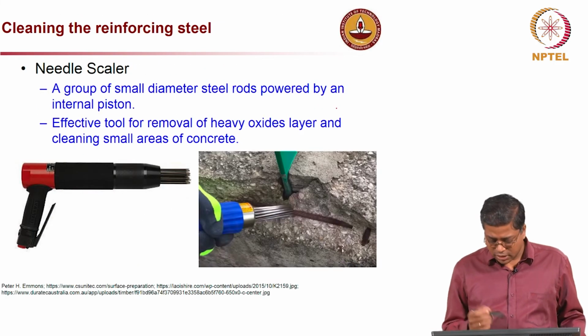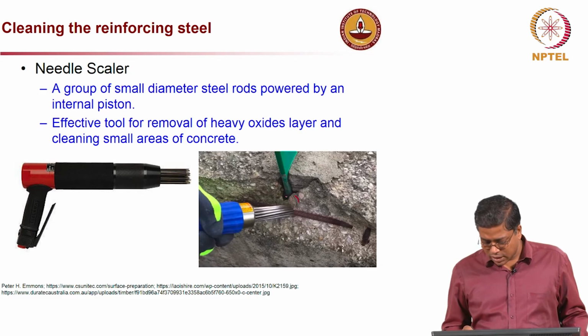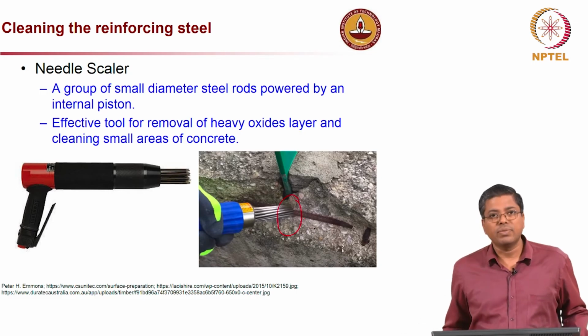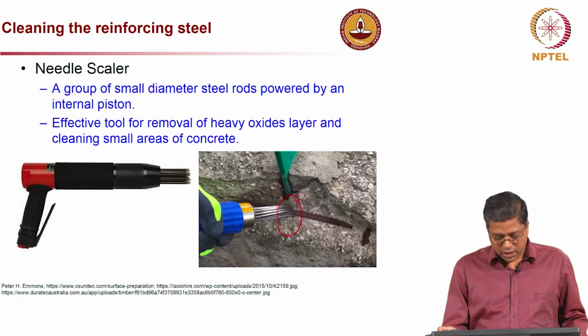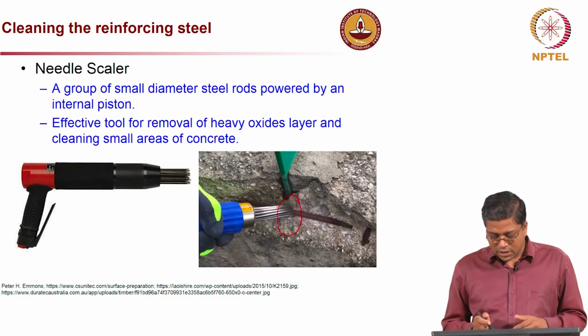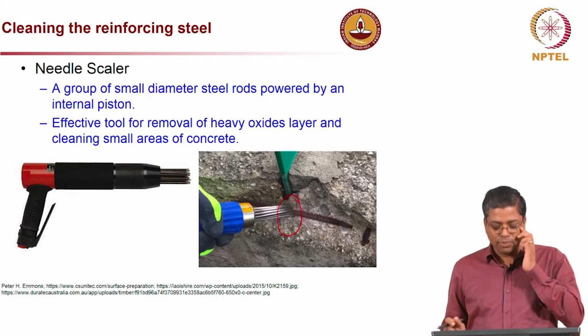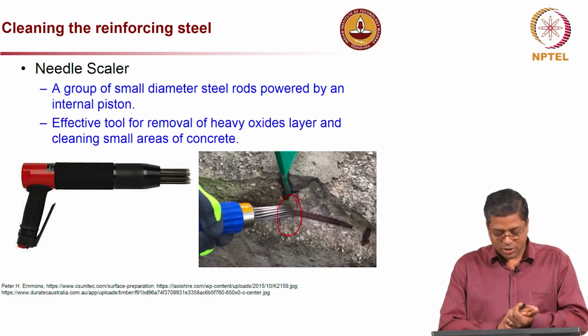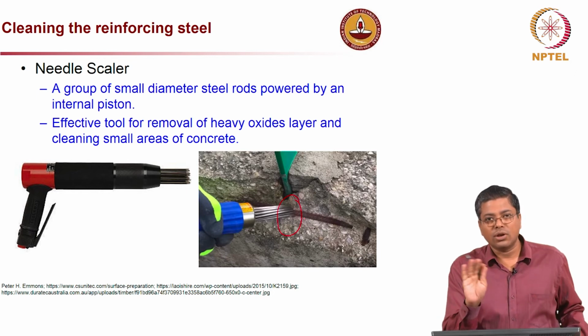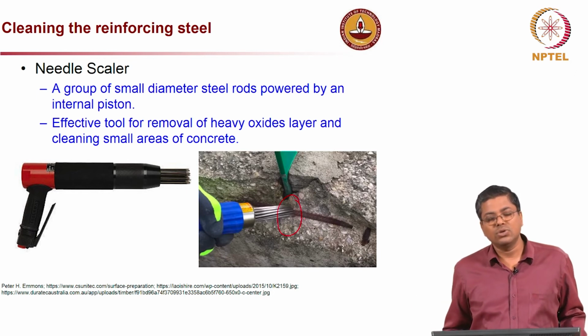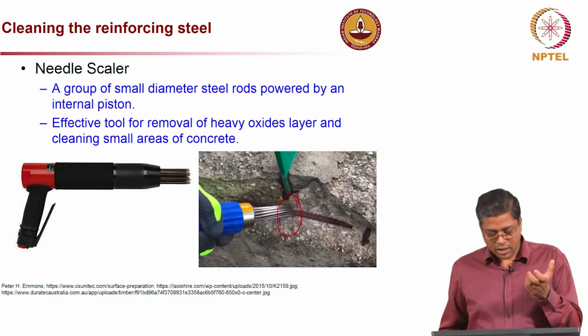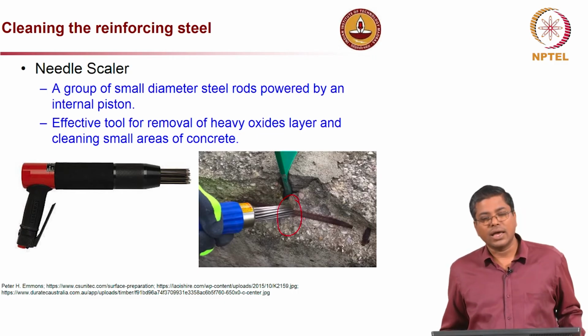Now, this is another needle scaler. You can see here they are used to clean the rust from the steel reinforcement, and these are also available in different power ratings. So, imagine using a tool like this to clean this rebar. If you tell a person to take a wire brush or an emery paper and clean the rebar surface, you will not be able to remove the thick, heavy oxide layers or the heavy rust on the steel surface.